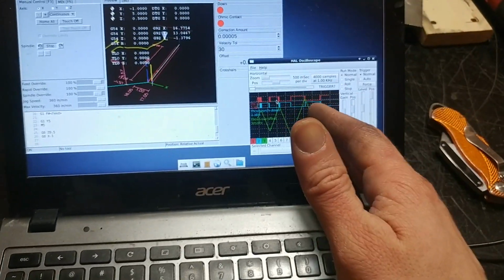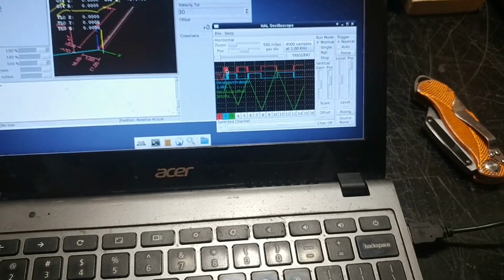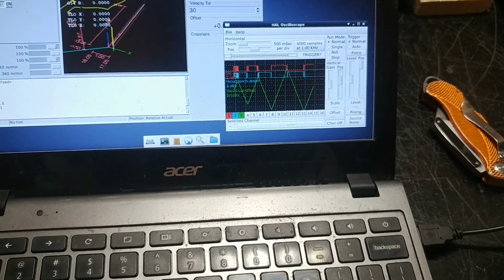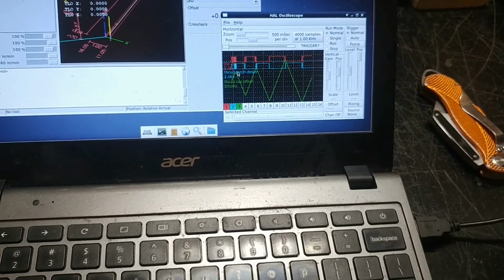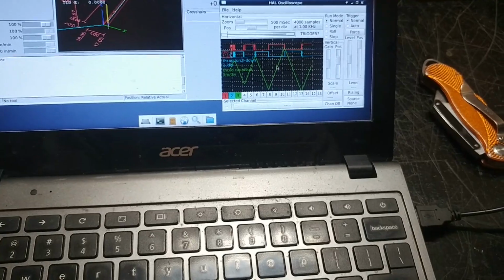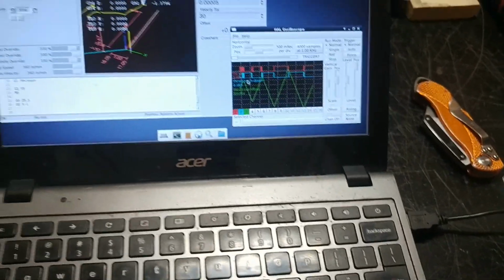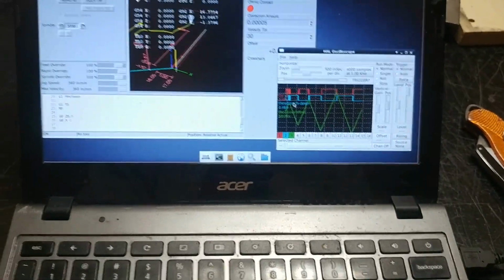Anyway, so now here's the halscope output, and you can see, basically, if the signal for torch up is high, then this one's low, and they swap cleanly one and the other. And what that ends up doing is taking the offset and makes it seesaw further and further as you overshoot more and more each time. So that is not what you want, and halscope lets you see just how badly it's operating.